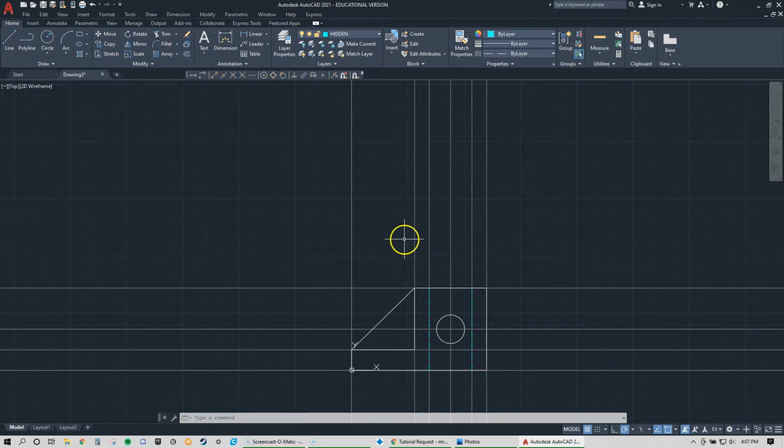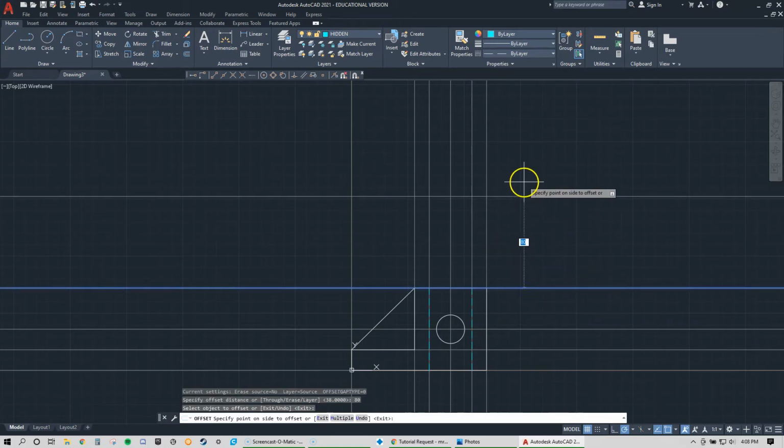Now, let's create the top view. This thing is 76 deep. So I'm gonna go O, enter, and I'm gonna kind of estimate how far up I want things to move. I can always move this later. Alright, so the whole thing was 72 tall. I like to at least space things out, at least the height of the piece if I can. So let's go with, I don't know, let's go with like 80. And let's click this line, let's move it up.